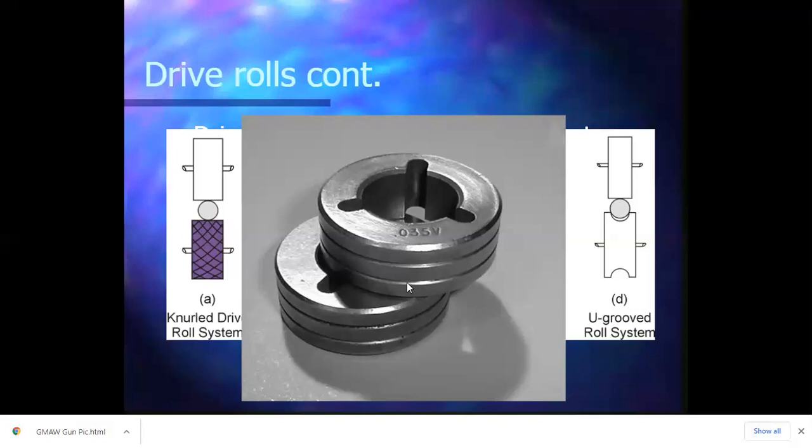That means this back groove here is going to be 0.035 of an inch. If you flip it over, you'll see 0.045, and this groove here will be 0.045. Sometimes you have combination rollers. That's just so you only have to buy one set. It can do multiple jobs. Sometimes we have dual 035 rollers. So if you don't see an 035 stamped on the other side or an 045, it means both of these grooves are going to be the same size.